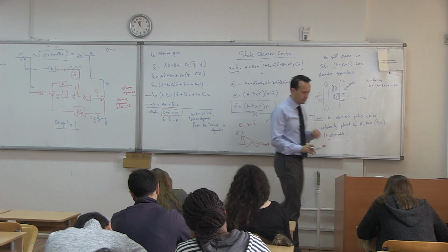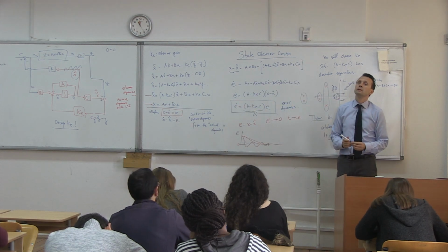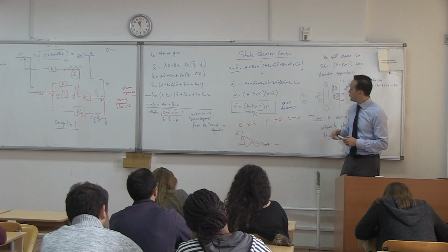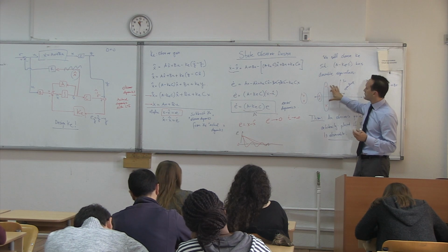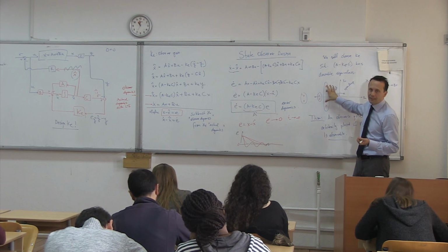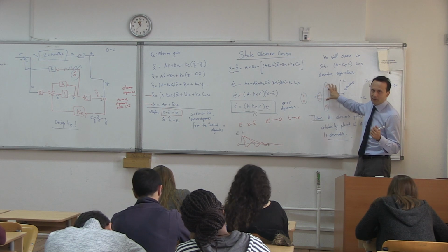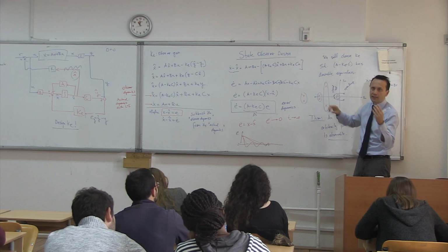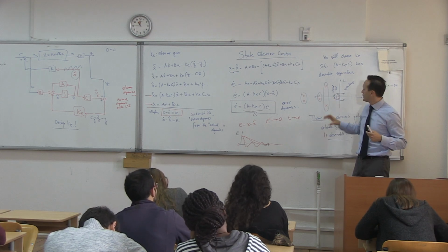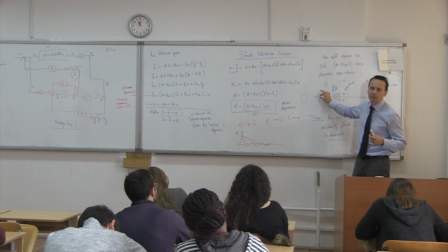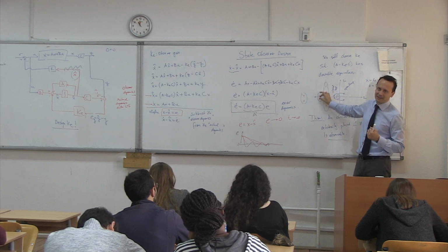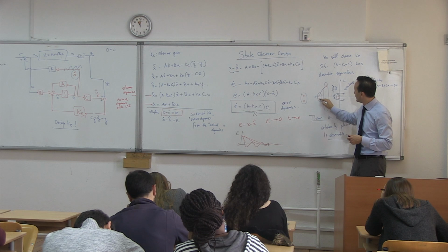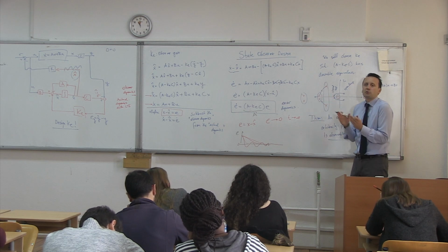Why didn't you put the poles onto the real axis to cancel oscillations? I'm sorry? You put it on the real axis? Yes, you can, of course, but since I chose two of them, like two conjugate pairs, sometimes the imaginary parts cannot be exactly cancelled to zero. So I always find it safer to say they are very close to the real axis. So I'm bringing these guys as close to the real axis as possible.